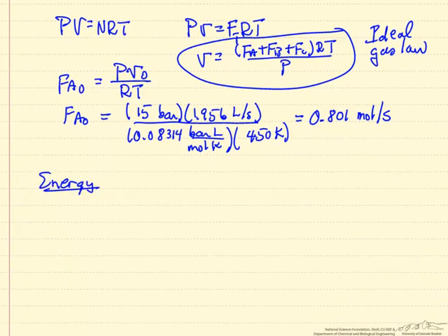And essentially, if we look at the heat capacities, we can see the heat of reaction doesn't change with temperature because the heat capacities with the stoichiometric coefficients sum to 0. In other words, CPA, where A is the reactant, so we put a minus sign, plus CPB plus CPC is 0, which means delta H is independent of temperature.